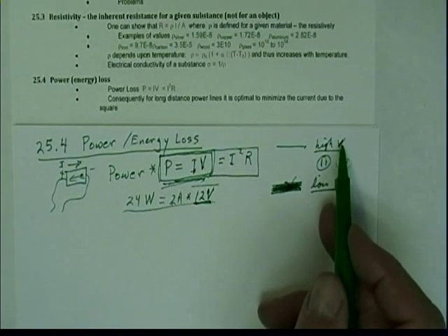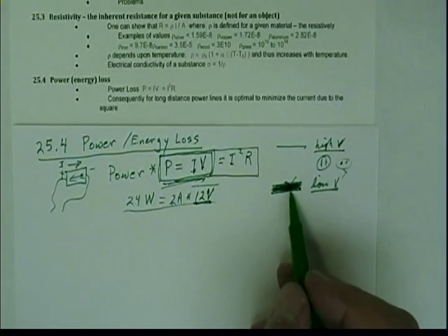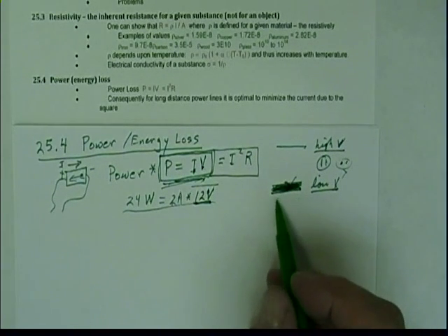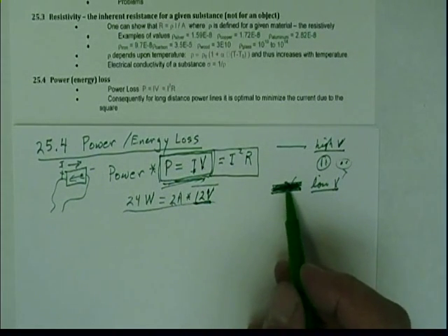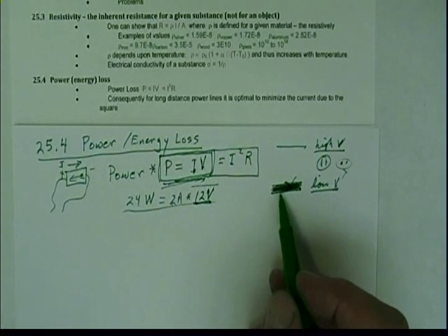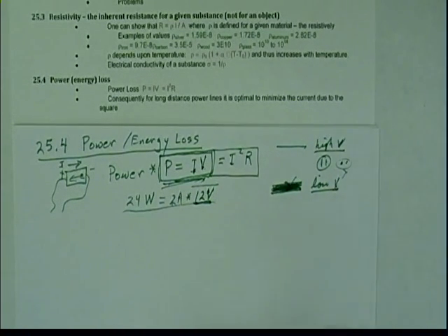So whereas electrocution is a problem with high voltage, fire is a problem with very, very high currents. Many of you have felt a wire that's been attached to a battery when you try to jump start another car. And if those are cheap cables that are not very thick, that can get incredibly hot and burn you. So you know the danger that's involved there.